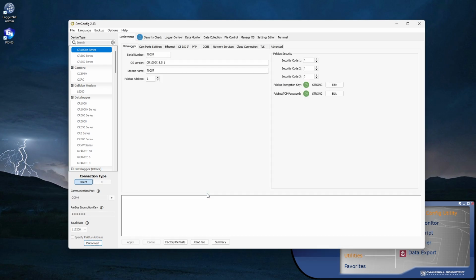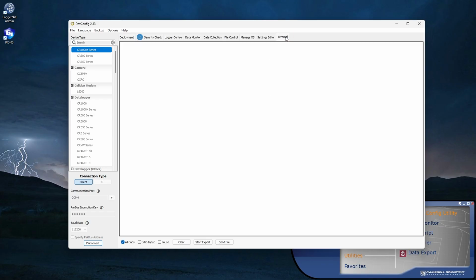The Connect Screen terminal emulator can also be used. Press Enter once or twice to get a terminal prompt. Type SDI-12 to enter SDI-12 mode. I'm given the choice of which C port to access. I am connected to C1, so I type 1 and press Enter.